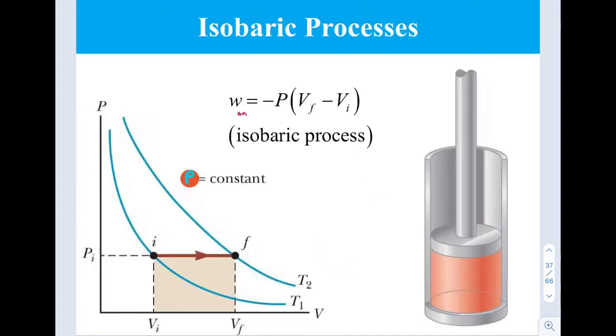So for isobaric processes, represented by a horizontal line on the PV diagram, the system experiences changes in volume from the initial state to the final state, as well as temperature, initial temperature and final temperature. However, the pressure remains the same. Technically, how do we make the system have constant pressure? We can set the piston to be freely movable. Therefore, any changes experienced by the system can move the piston upward or downward freely.